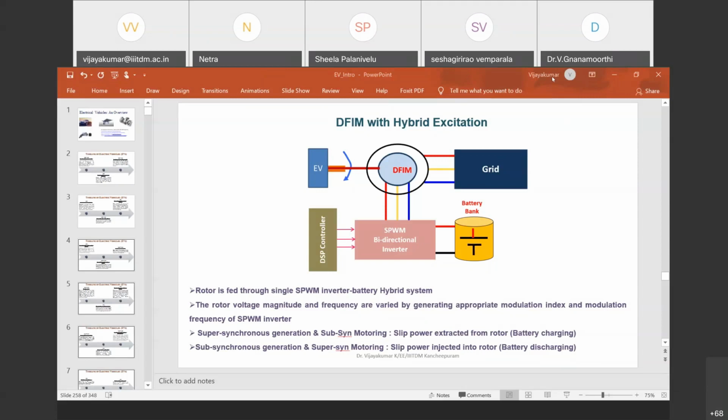For that, again, we have to go with power converters. We cannot directly parallel these two. For that, you need different charge controllers for the battery, and another charge controller for the supercapacitors. In that way, you can hybridize your energy storage. When we come to the life cycle, the life of a supercapacitor also depends upon the material you are using. Even people are working on it.